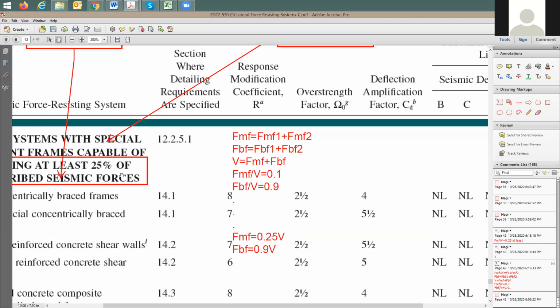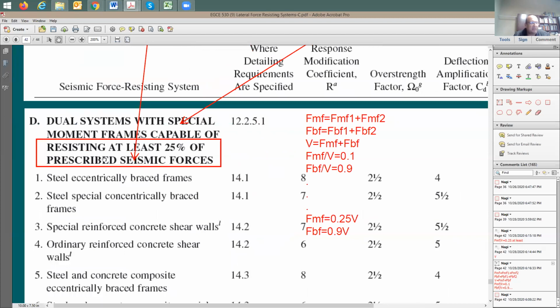Our force is more than the shear force, it is not a safety factor. It is confirmation of the code. It's the limit in the code when it comes to moment frame design that your moment frame needs to be a little bit larger. Yes, but I wouldn't call it safety factor. I'm going to say this is an emphasis or confirmation that your moment frame is going to be good enough to be able to act in a ductile manner.